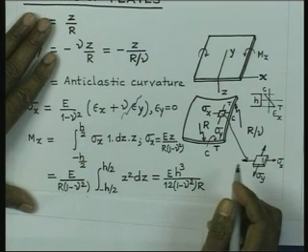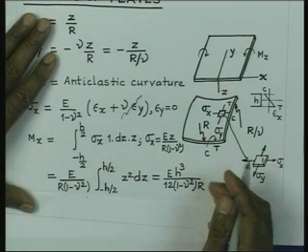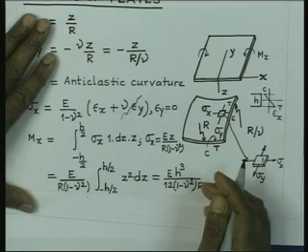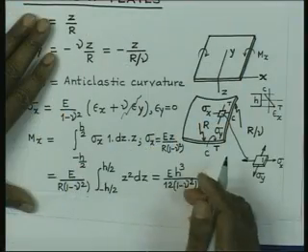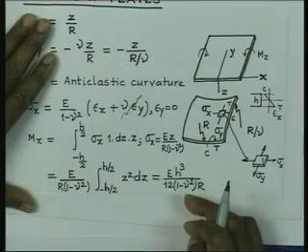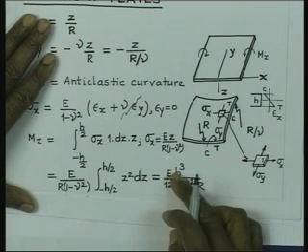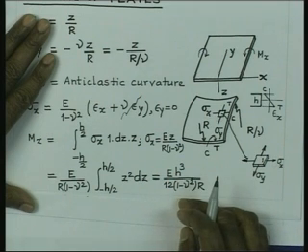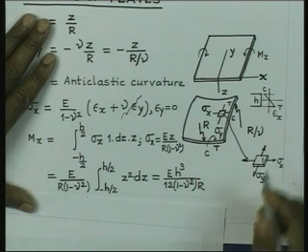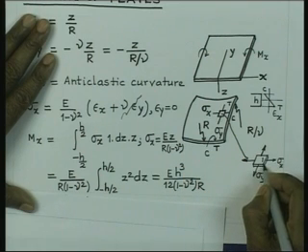into r. You remember in the case of beam, we had mx is equal to E by r into I. So, we have a similar expression here that mx is equal to E by r into this quantity, which is nothing but equivalent to I. You have a plate of height 1 and width 1.